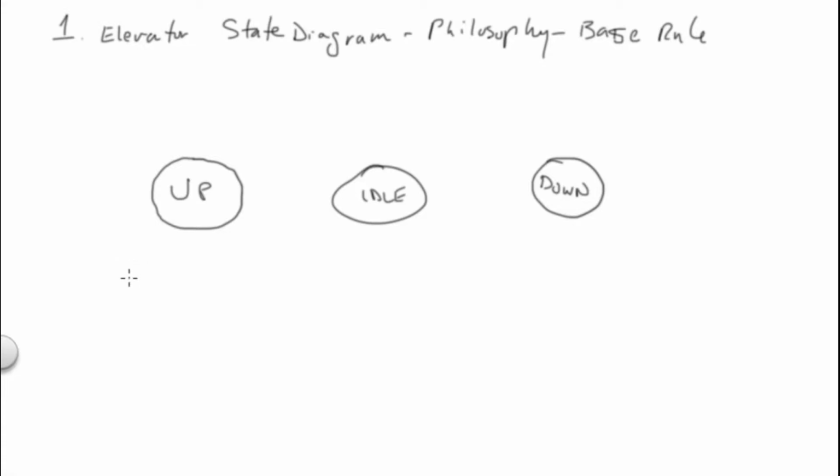So basically, at each floor you have 3 limit switches, one just above, one right at, and one right below. So if you're coming up and you hit that one just below it, and you're going to stop at this point, and you're in the up mode, you go to another state. At this point, when you hit that limit switch, you go to a slow or like a dribble state, and then you stop at this point.